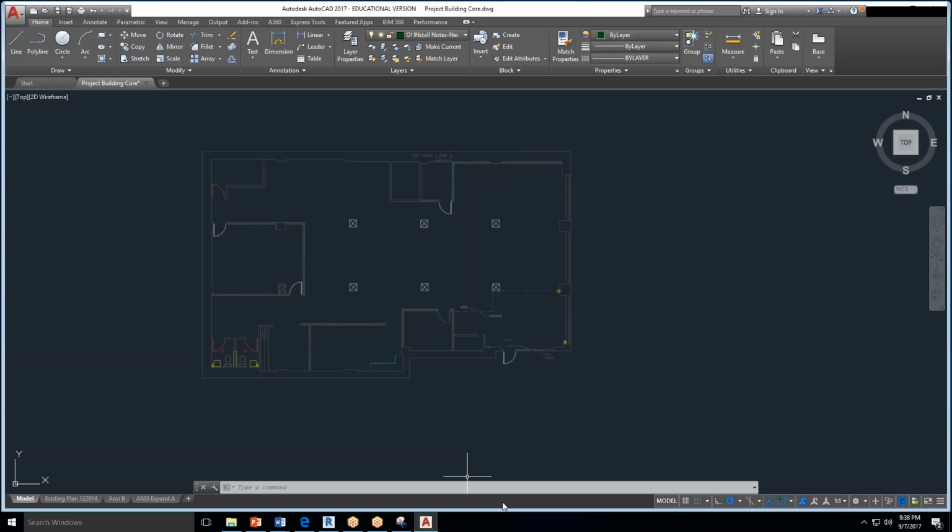So it's asking if you want it on level 1, where it's going to take the very bottom edge of the roof and put it on the ground because it's building from the bottom up, or if you want to move it to the top of level 1, starting at level 2. So you want to choose level 2, and then it'll put it where it needs to be.